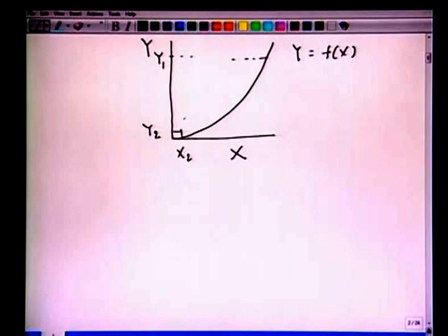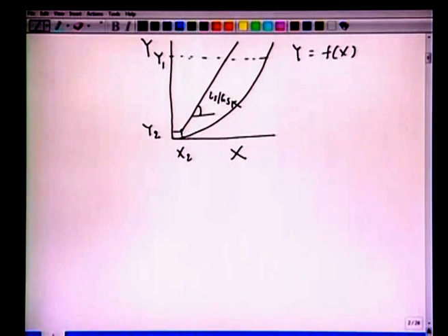and x1 is not known here. If we draw an arbitrary operating line with the slope of Ls by Gs, this will intersect y equal to y1 here. If we decrease this Ls given Gs, so if Gs is fixed and we want to decrease the amount of Ls, then the slope will decrease till it intersects this y equal to f(x) curve, which gives us Ls by Gs minimum, from which we can calculate the amount of solvent required.